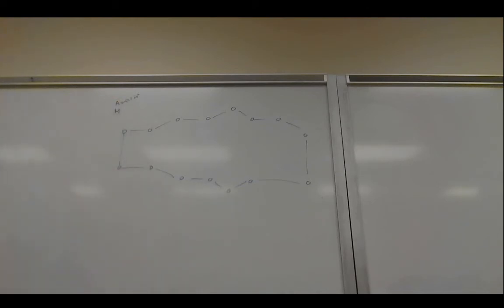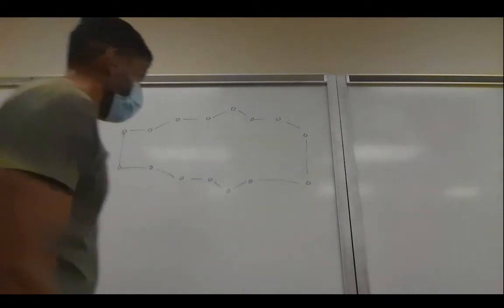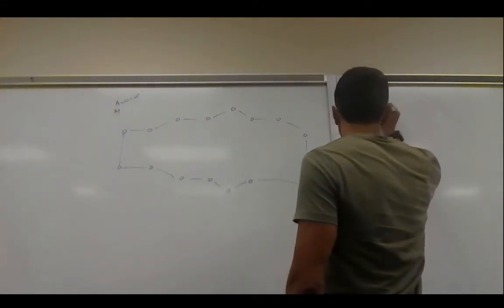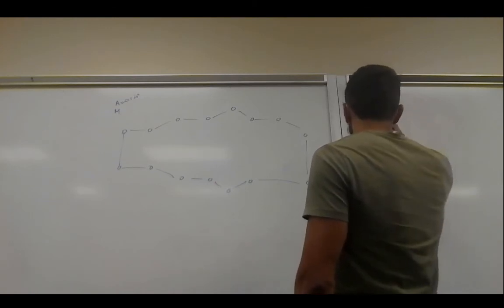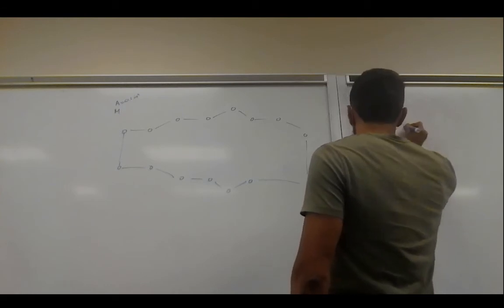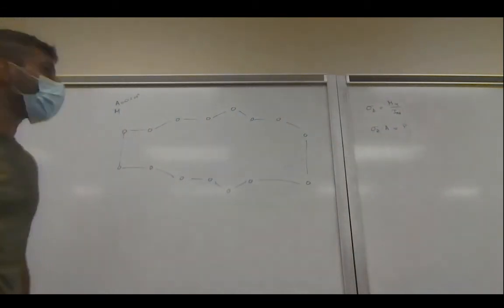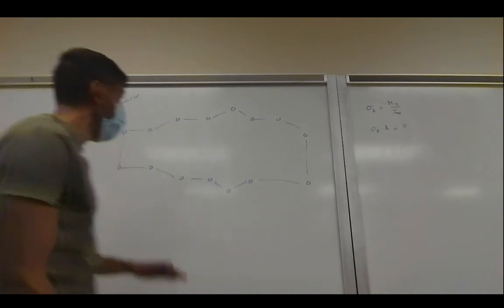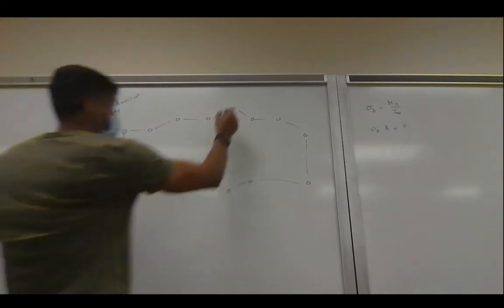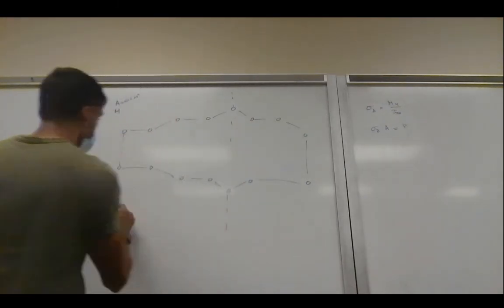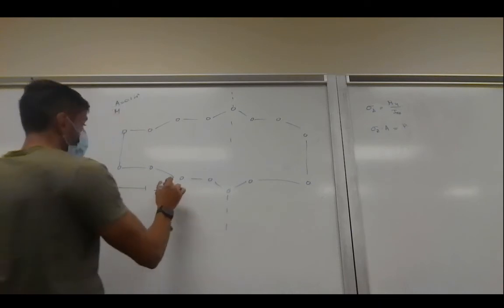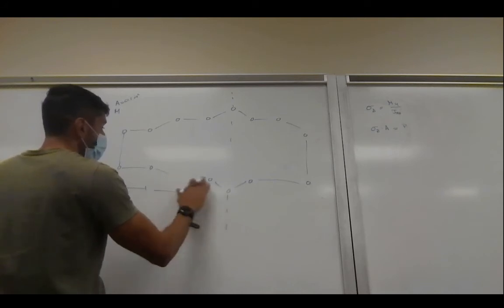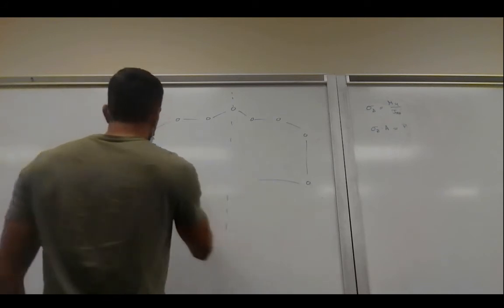Okay. And you were asked to calculate the load, and load was specifically asked for. So that means again, you use your stress equation, M times y over Ixx, and you multiply this by the area to get the force, the load in the sections. So what you have to do for this, you have to find the centroid. You know it's symmetrical on one axis, so you do know that. I think this was 5, 5. I think the bottom's all flat except the center part. That's true. It was not double symmetric. You're right.